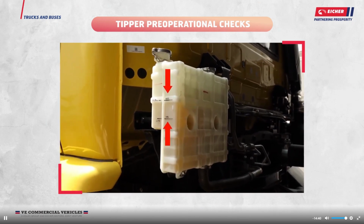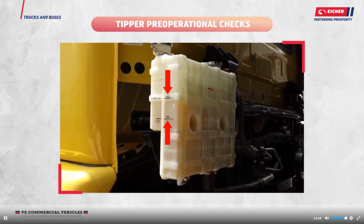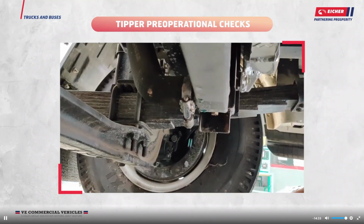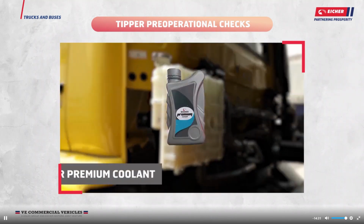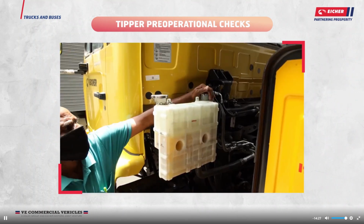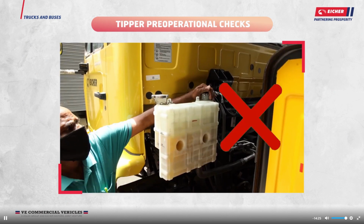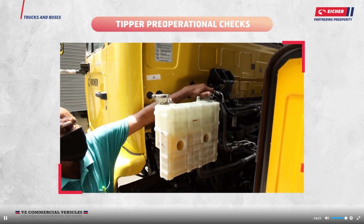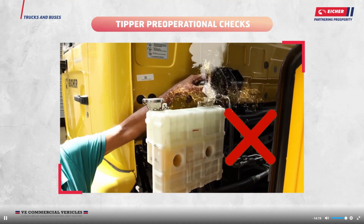Check coolant level in the reservoir tank. The coolant level should be in between maximum and minimum mark. If the coolant level is below the minimum mark, check for any leakages. Correct it and top up with EICHER Premium coolant. Caution: do not open the expansion coolant cap with a hot engine. Burn injuries could occur due to the steam of the pressurized water being released by removing the pressure cap.